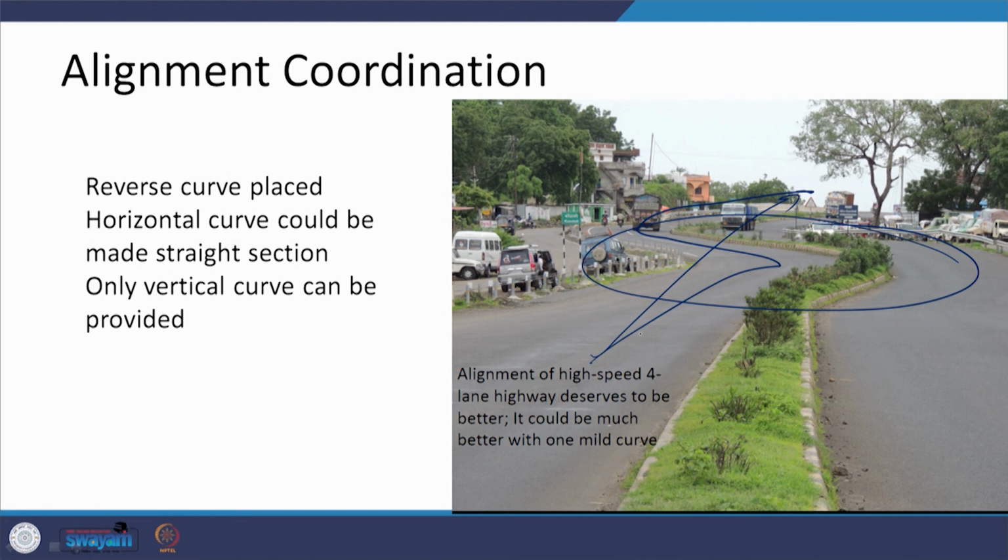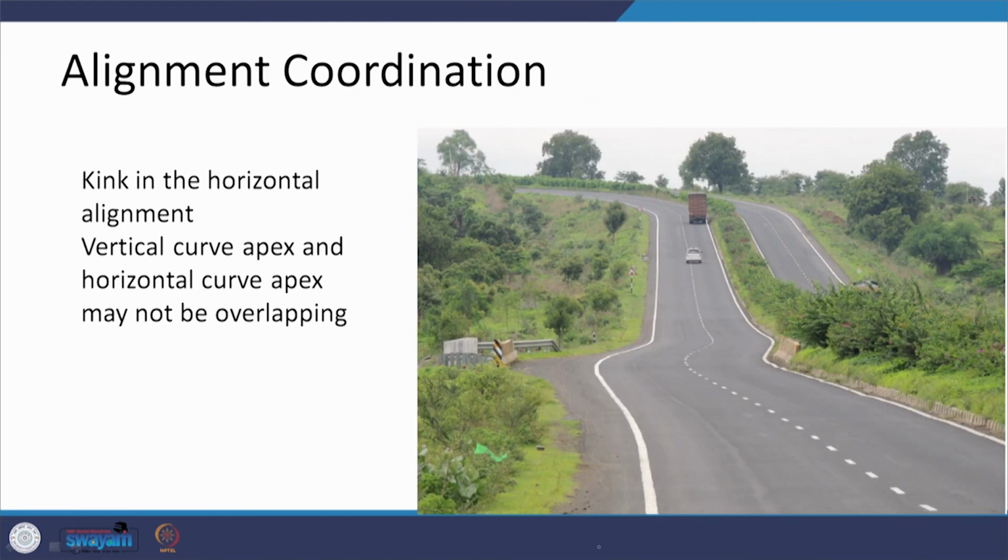And then when you are going from this to another one, here at this point there is a sort of curvature. This could also have been omitted by way of a straight grade and a vertical curve, and that is where things would have become better. Here again what we can see is this type of kink which could have been very easily omitted, and then we are going up, then you have a straight profile and then a curvature here, but at the same time the gradient is also there.